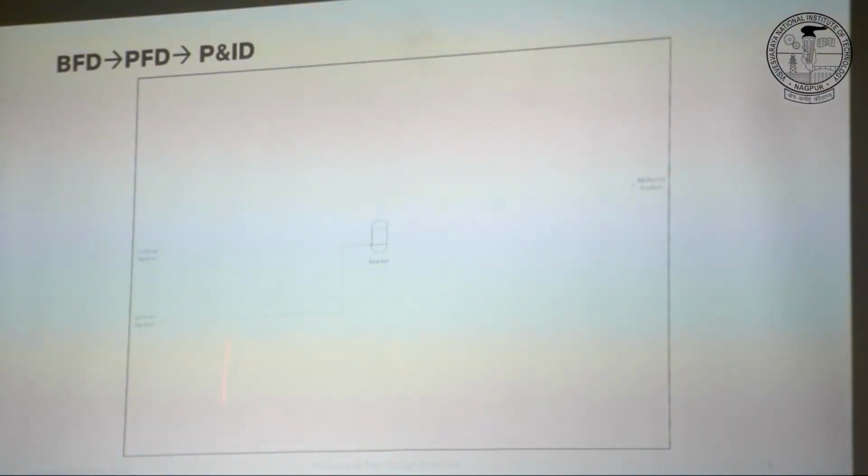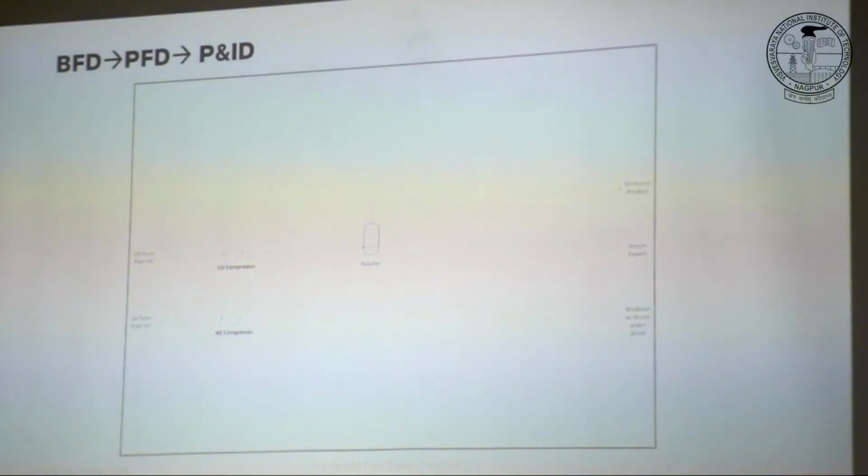So we start with, as we always say in our onion model, the reactor, the reaction system. So carbon monoxide, hydrogen. Sorry, it's not very visible. First thing, we had a look at the operating conditions. That means we have to bring our reactants to 50 bar. A few minutes ago I said we can use one compressor, but here you see I even had two compressors. So you compress your reactants to operating pressure, then go to the reactor.